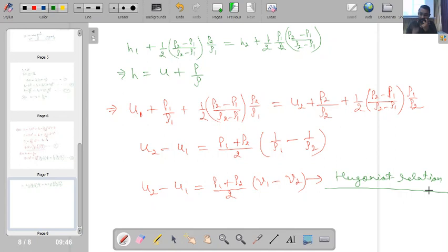One important outcome of this exercise is that when we analyzed the Hugoniot equation, we considered that our wave was fixed and the fluid was moving. In this derivation, we have considered that our wave is moving and the fluid on one side is stagnant. After the wave passes through the fluid medium, it imparts motion to the fluid.